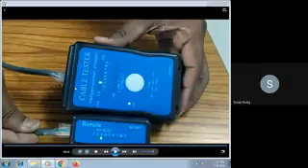We are attaching one end to this tester and another end to this tester. Whether all these wires are prepared to send signals or not, we are testing with the help of the cable tester. One is acting as a transmitter and one as a receiver, and whether all the wires are properly fitted in the connector or not will be displayed by blinking this particular light.